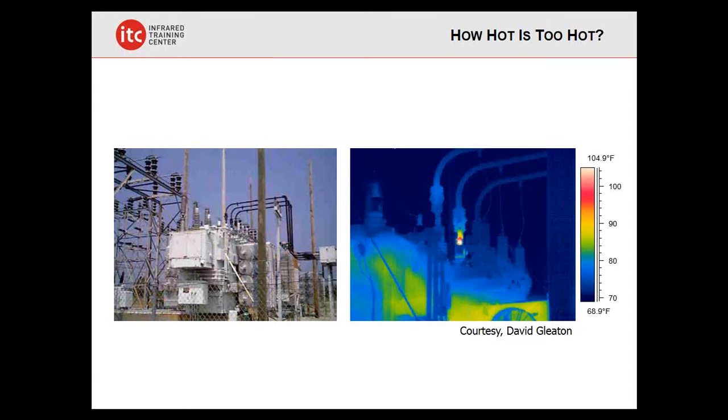Yeah, that's right. You have to look at what kind of equipment it is, and if that equipment fails, is it a big safety hazard or a big operational hazard, such as taking down an entire plant? So, sometimes the lighting panel, which we may not think of as being very important, could be extremely important. For instance, if that lighting panel happens to serve an operating room in a hospital and the lights go out, that's pretty important to the patient.